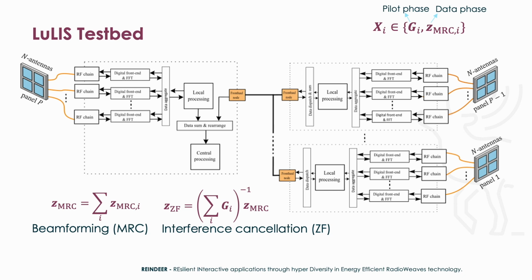We should note that implementing zero forcing requires performing a matrix inverse on the aggregated data at a central processor, whereas for maximum ratio combining, the aggregated data can be directly used to extract the user information without any centralized MIMO processing.